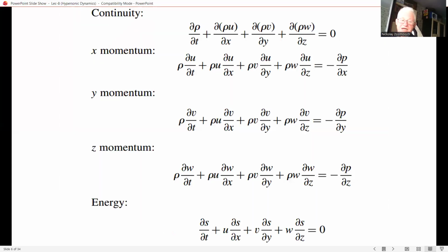Part of obtaining the best accuracy is to use the full continuity, momentum, and energy equations for fluid flow with no geometric simplification, right? If you are satisfied at first with the assumption of an inviscid, non-chemically reacting flow, then these equations are the ones you want to use.